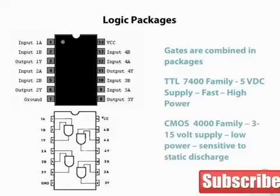CMOS stands for complementary MOS and is growing in popularity. CMOS once had the disadvantage of being slower than TTL, but now we have high-speed CMOS which rivals TTL for speed. CMOS also consumes much less power than TTL and can operate on a wider spectrum of supply voltages, typically 3 to 15 volts. CMOS does have one drawback, in that it is vulnerable to being damaged by electrostatic discharge.